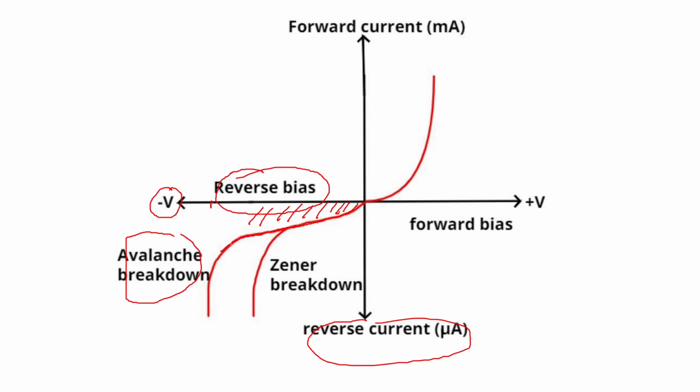So in the first case, you see avalanche breakdown happening, and the avalanche breakdown is shown like this. In the second case, you see this breakdown happening here. So this is your Zener breakdown, VZ. It is happening a little early because of the electric potential of the depletion layer in the Zener, because it is heavily doped. And here you can see this is a sharp breakdown at a particular voltage.